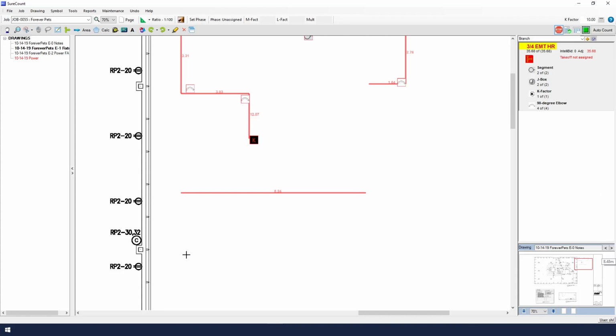If we want to measure some more below this line without connecting our third point to the second point, but we don't want to click Stop to do that, we can also right-click and use the Break Measurement feature. It will break us out of that initial measurement to move below and start a new measurement, which can be of that same size. We'll repeat those actions a few times. Again, this is just allowing us to break out of the current measurement to then begin another one if we need to. When finished, we click Stop.